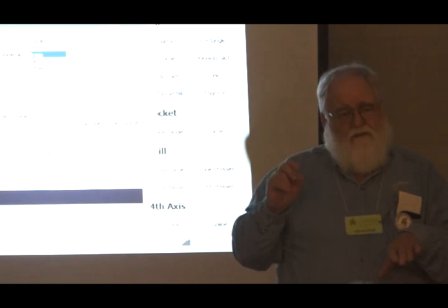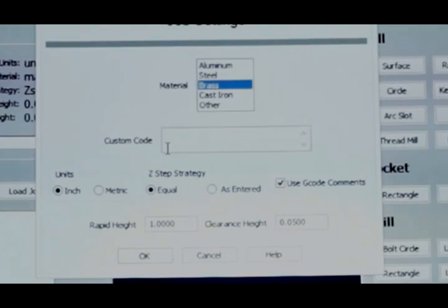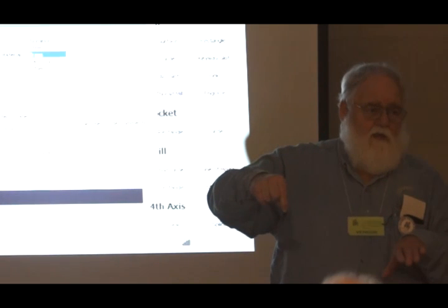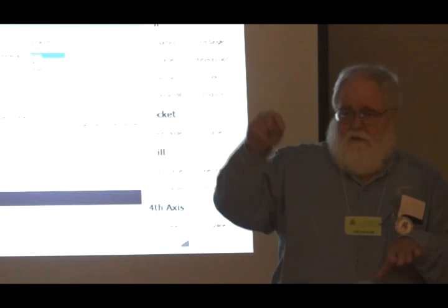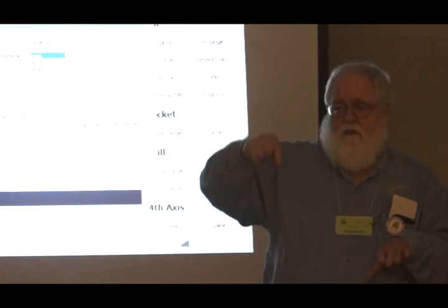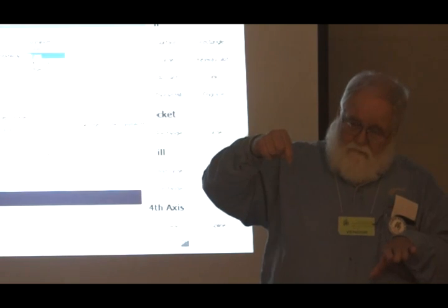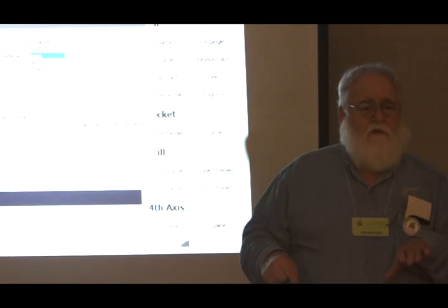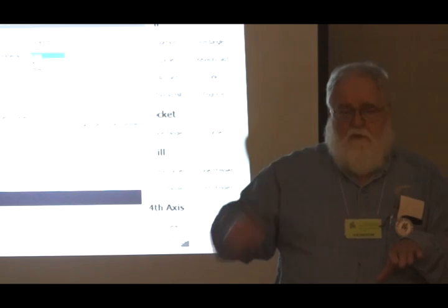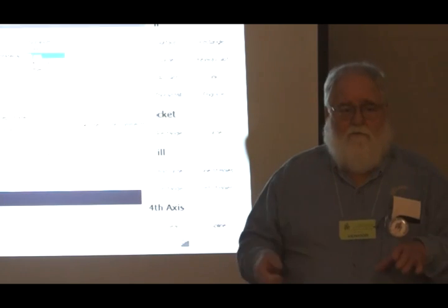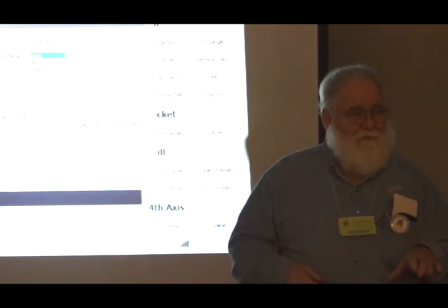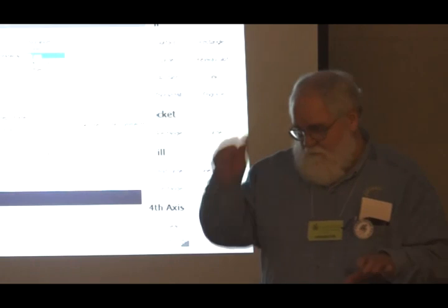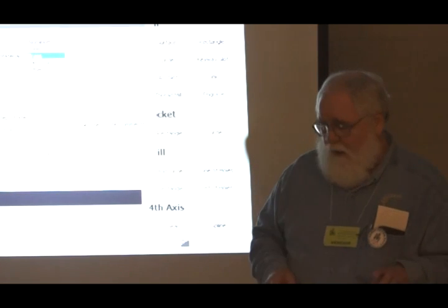The clearance is really a distance. I really ought to say distance instead of height, because it'll go down until I am 50 thou away from my new cutting surface, and then it'll slow to feed rate and move in there. So you don't see it, like some of the old things, where your plunge rate is feed rate and you're watching it plunge down 1 inch at feed rate. I'll go rapid down to 50 thou above the work, or 5 thou above the work, depending on how gutsy you are. I can't watch a tool go that fast. So you're putting in a clearance height, and again, this will be a job-wide value.